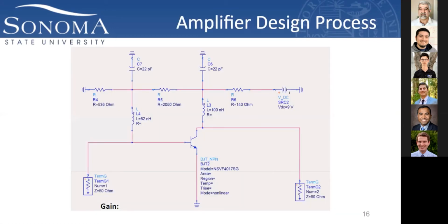So once we were able to confirm that we could generate our 915 megahertz signal, the next step was to amplify it. Given the FCC limitation of 1 watt deliverable to the antenna, we were aiming for a gain of around 30 dB, given our 0 dBm input. This is the base amplifier design that we transferred to a PCB design that we ordered and tested.